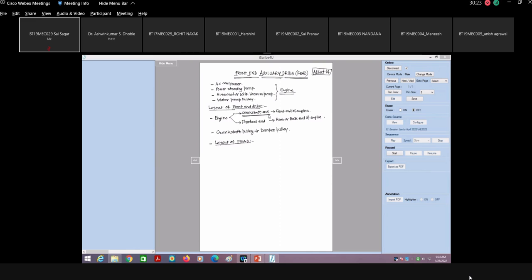Okay, that is frequency of vibration, it is common, but what exactly do you mean by it? If I say that a third order harmonic is present in this particular mode, what do you mean by that? Frequency of vibration, Prajwal, that is okay, because we are discussing vibration. It is an integral multiple of the natural frequency, yes. So the second harmonic means it is 2 times the first natural frequency.